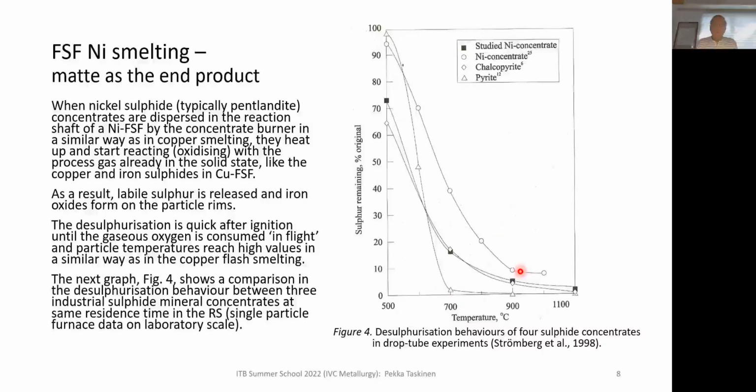So this is the reason why we generate a lot of heat in the reaction shaft, and why the reactions, due to the very fine dry feed material, are very quick, and they complete their reactions with the surrounding gas in the time span available in the reaction shaft, typically 2.5–3 seconds as a total flight time.